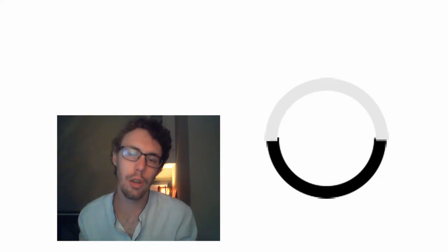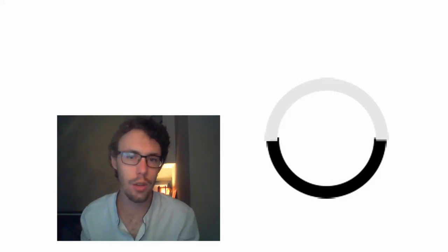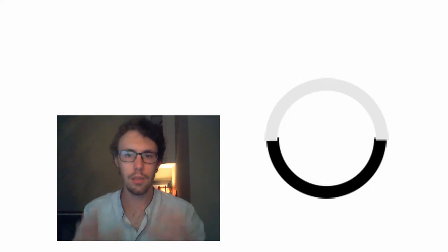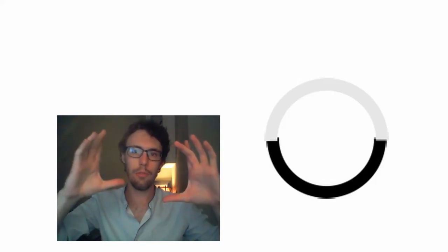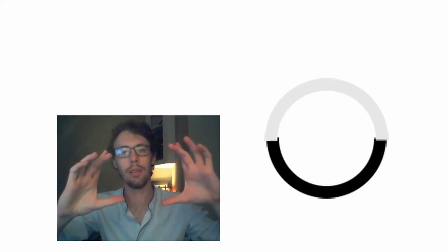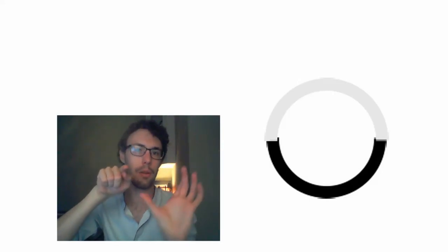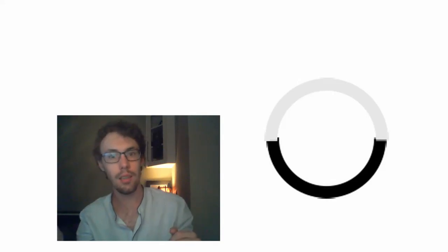Then you get two types of encoders, basically: an absolute positional encoder and an incremental encoder. The absolute positional encoder works with Gray code. It's basically take a circle, divide it in half, make one side black and the other side white. If you shine a laser and the circle turns, it'll either be black or white, right? So you know it's either in this 180 of the circle or that 180 of the circle.